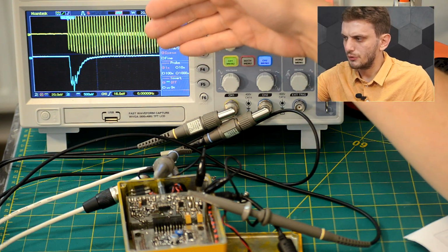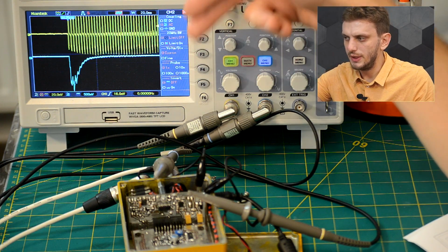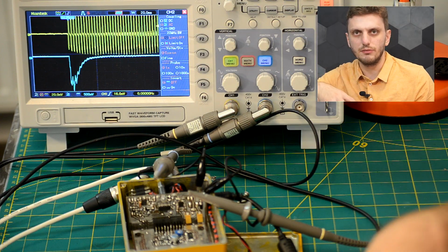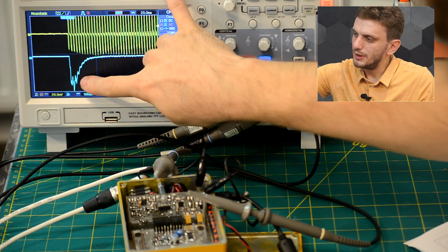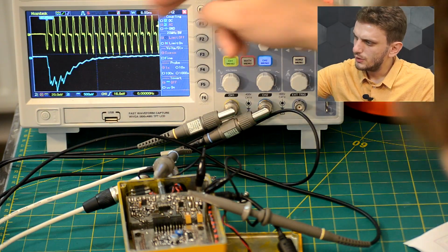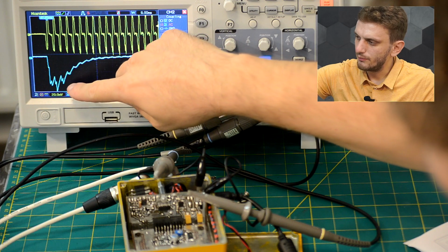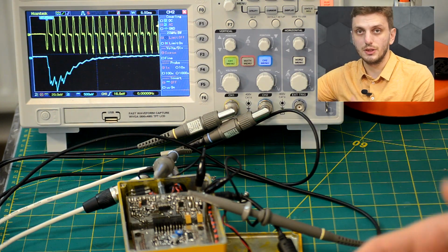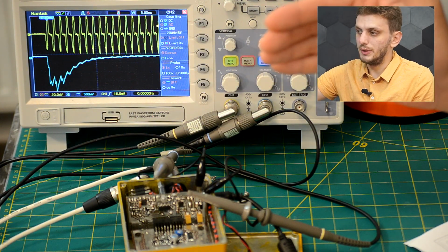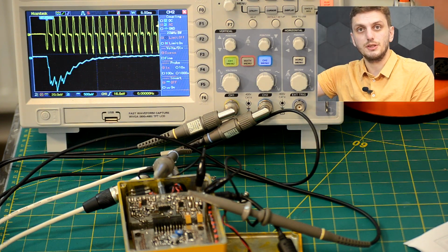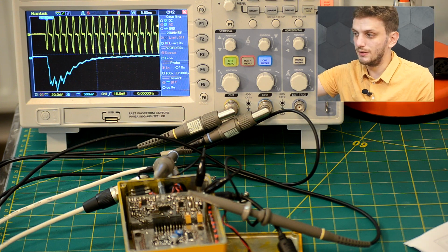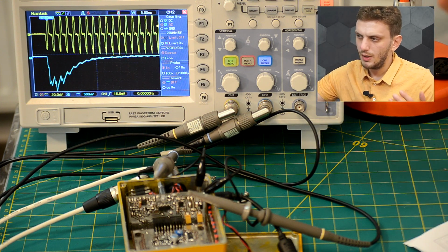Now to get a better reading, I set my second channel to AC coupling, so we can't see the exact DC value, but what we can see is that the voltage is oscillating. Every single peak causes a direct indentation in the voltage on the capacitor. When the peak is hit, the capacitor is being discharged. Then the capacitor slowly charges up, and then the next peak hits, and again the voltage drops.